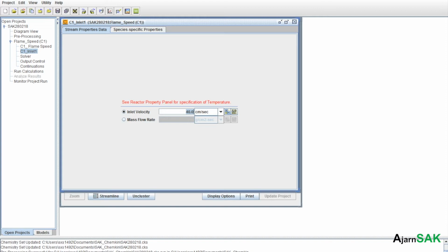It goes here, but your velocity will keep it in the middle. So this flame speed equals the velocity. It will do that automatically? Yes. This kind of reactor is based on combustion here, so you have to hold the flame in the reactor. So this is an estimation for the first iteration of what your velocity is. It's based on the velocity of your flame. So 40 centimeters per second is alright.